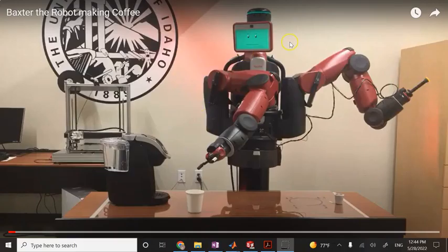So here is the robot. Now sometimes the robot has 2 arms, sometimes 1. In this case, it has 2 arms. Each arm has 7 degrees of freedom, and we call it redundant because, in order to achieve 3 positions and 3 orientations at the end effector, you really only need 6 degrees of freedom of the robot. So when the robot DOF goes beyond 6, we call it kinematically redundant. And this one has 7 degrees of freedom. As I said, all joints are revolute joints.